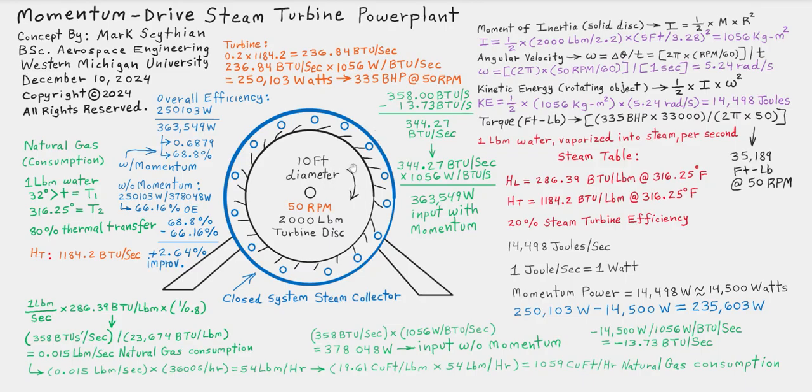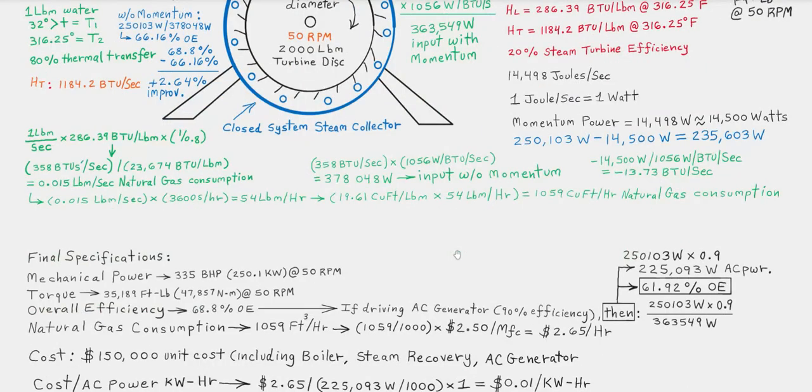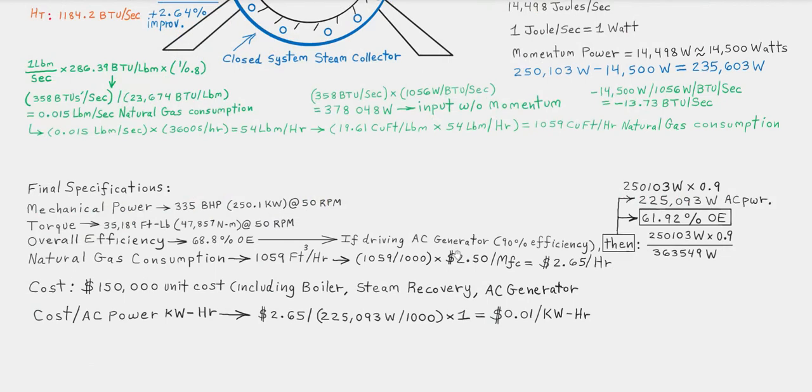We'll have to do the ratio on the gearing, but one turn could then generate 15 or 20 turns, because it would be like high gear, but we have the torque to do it. So much torque. So that's a better idea, to have it slower turning at higher torque, and then we could use the gear step up system to drop some of the torque and increase the RPM. You might need to do that if you're working with certain industry standard with minimum RPMs for that generator, which you probably are.